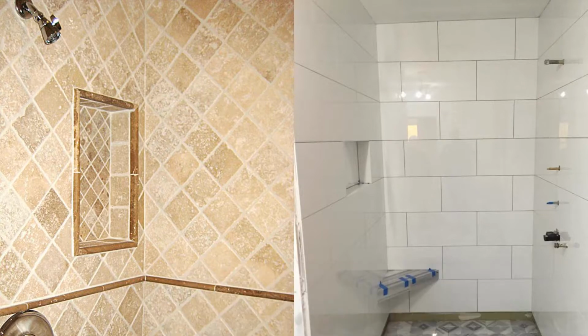For example, if wall A intersects with wall B at a 90-degree inside corner, with both walls being laid out at the same time, the layout will be correct. However, when the tile on wall A is installed first, the left and right cut tiles on wall B will not be equal. The left cut on wall B will be smaller than the right cut by the thickness of the tile installed on wall A.